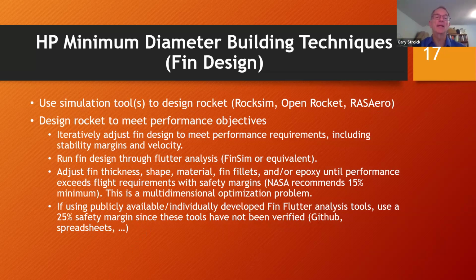Look at the next step that you're going to need to follow, and that is to run the fin design that you come up with through a flutter analysis, a fin analysis. There are tools available either online or on GitHub for fin flutter analysis. There's one called FinSim that can be purchased for a minimum amount of money. I believe $35 is what it used to cost. I think it may no longer be available, but you just have to do a search and check on that. Some people have told me that recently.